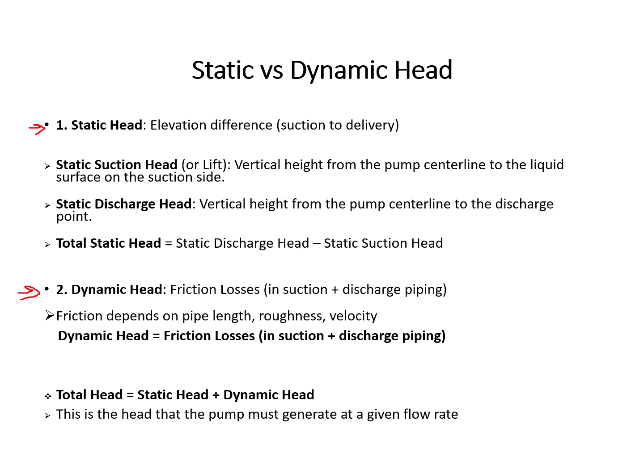Head is more than just height. Static head is the elevation difference, like lifting water from a basement. So it is an elevation difference. It is like the distance between the height and the delivery. And the static head is divided into suction head and discharge head.